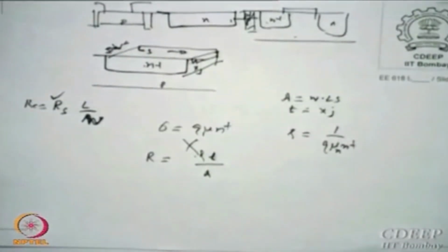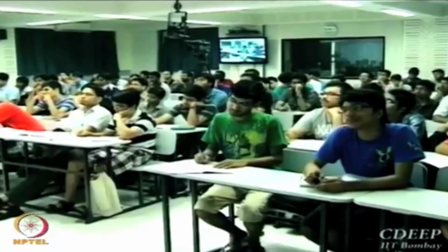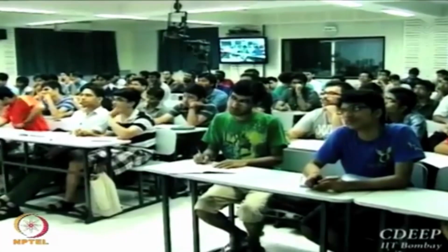I have a P region created in the P well itself, and make two contacts separated by length L to give my sheet resistance into L by W values. Why did I say P? P will have a higher resistivity and therefore higher sheet resistance.